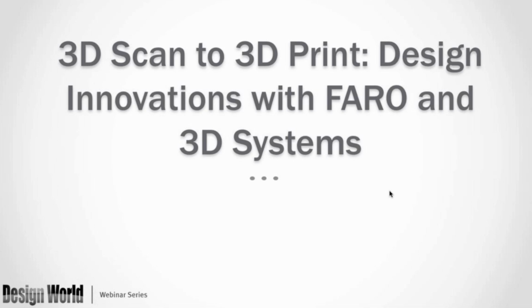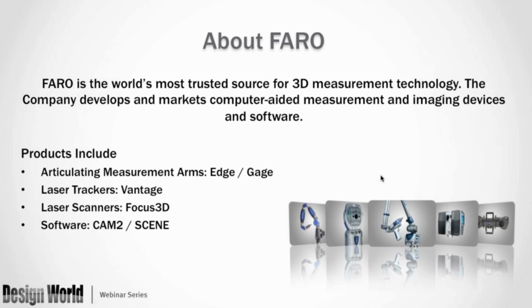So welcome to this presentation of the techniques and equipment that allow acquisition of as-built data on critical and key characteristics of legacy parts and how that can be integrated with the development of new and existing products. Faro has been providing digitization equipment to industry for over 30 years. Starting initially with small single-point tactile units, the range has expanded to include articulating measurement arms, such as our Edge and Gauge. These have lengths from 4 foot to 12 foot and the ability to leapfrog in order to measure larger parts. The user has access to high accuracy tactile and non-contact measurement with feature-based and point cloud capabilities that are ideal for small to medium-sized objects.